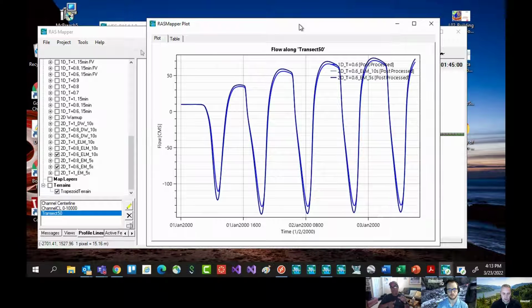Because what happens is as that wave comes in and moves upstream, it diffuses it, and it doesn't show the influence of the tide going as far upstream as it should. You're just showing one location here, but somewhere way upstream, the worse theta is, or if your cross-section spacing is too large or your time step is too large, the influence of the tide is going to diffuse out quicker, and it's not going to show up farther upstream. And a lot of these systems around the country, like the Columbia River, at low flow, you see a dominant tidal signal right up there at Portland. That's a long ways from the ocean.